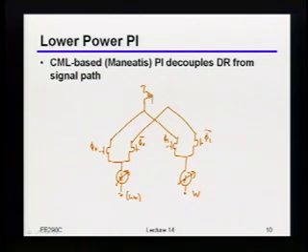So the load is actually quite simple. It's basically one PMOS device tied as a diode, and a second PMOS device tied with a control voltage. And of course, I'll do the same thing on the other side over here. Now, you don't just use this load by itself. What you're going to do is build another bias circuit that also uses that VC to make it so that the swing you see here is also set by that VC. So in other words, when there's no current flowing here, it's at VDD, and when the full current is flowing, it goes down to VDD minus VC.